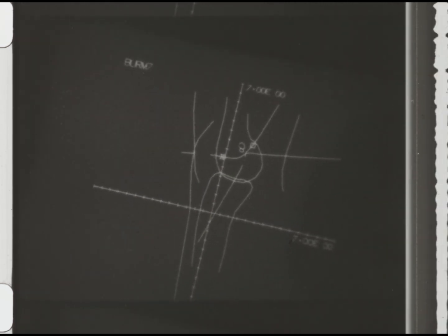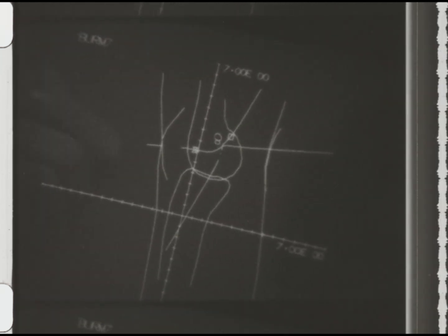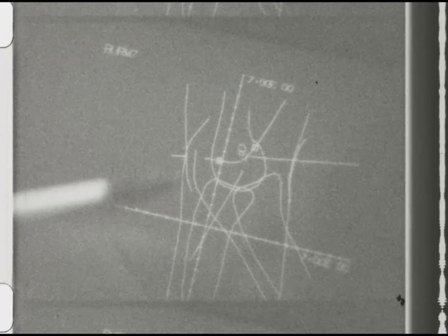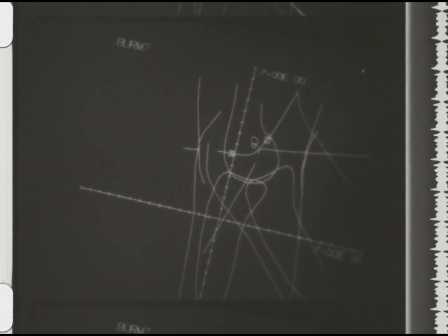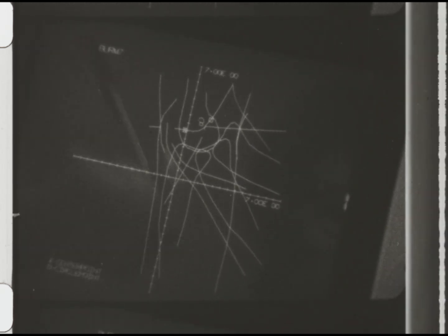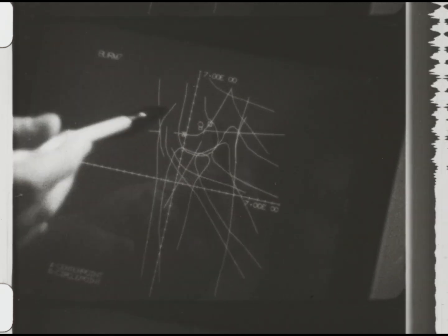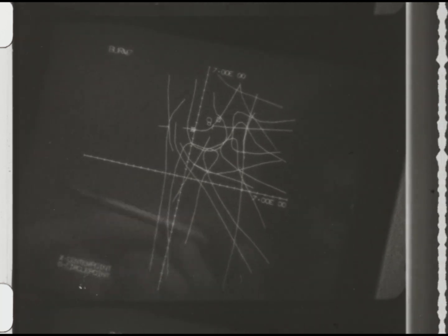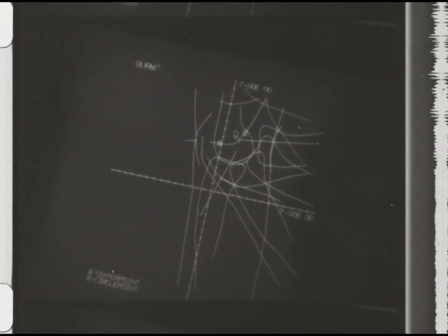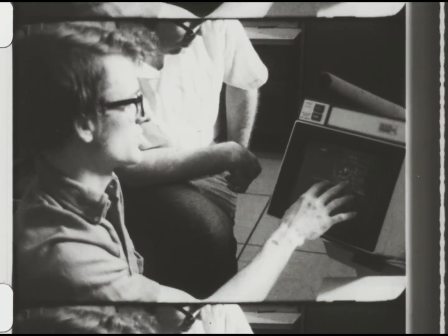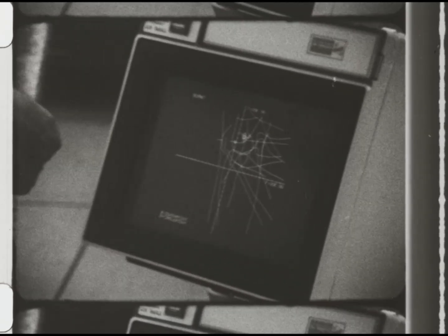And here we're showing at a larger scale these curves superimposed upon the X-ray data for the leg. Here's the femur, and here is the tibia in its different design positions. So, for instance, we now would like to know what are the possible fixed and moving pivots. How do these compare with one another? How do we match these up? With this particular plot, we know that any point out here will not be one we want to look at because it will be off the sketch of the leg.